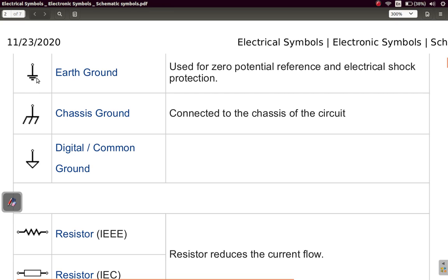You as an electrician would buy maybe a 6 foot, some of them are 4 feet, 6 or 8 foot ground rod, which is a copper rod. It looks like a bar of building steel, but it's smooth and it's pointed. And you use a sledgehammer to drive it down into the ground and then connect the ground wire to it by a clamp, right?